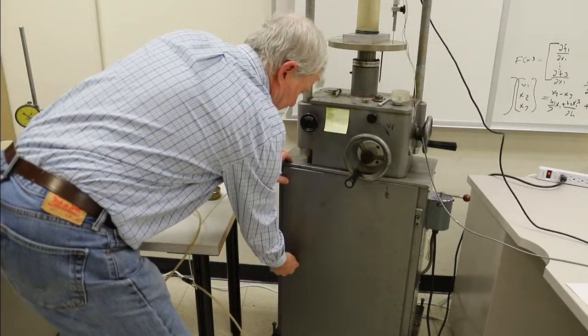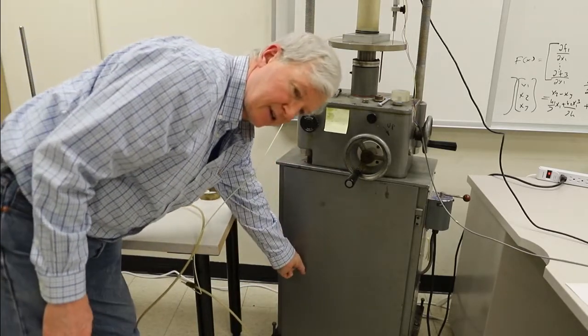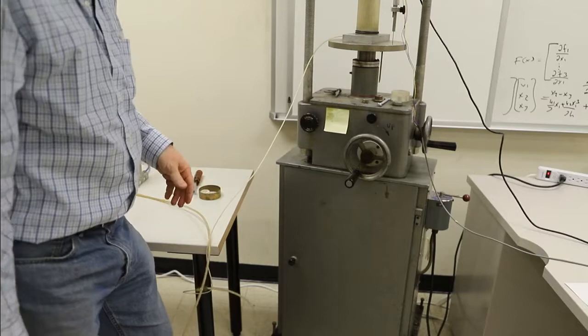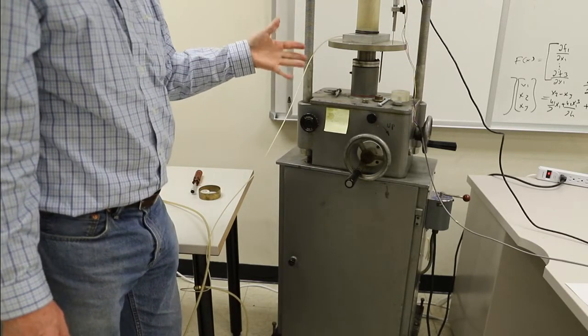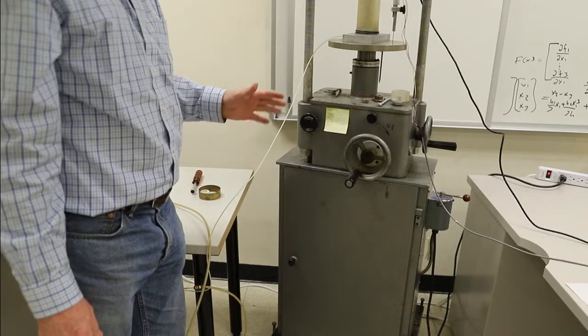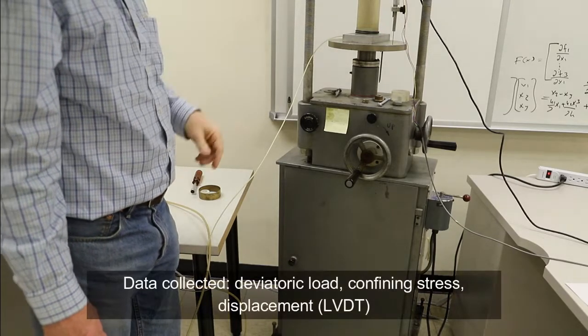The rate of deformation for a clay could be important in terms of the strength, for strain rate effects and things like that. But for a sand we wouldn't expect it will make much difference. At that relatively slow rate we could get thousands of data points for our stress strain curve, but we will not do that. We'll back off and take far less.